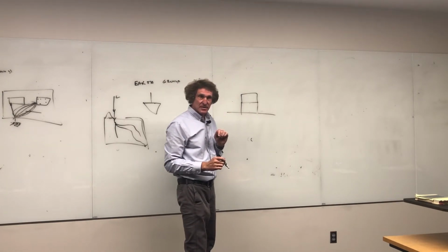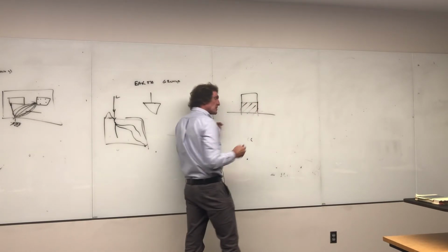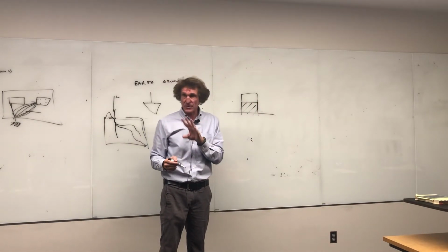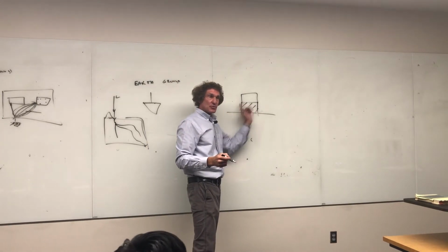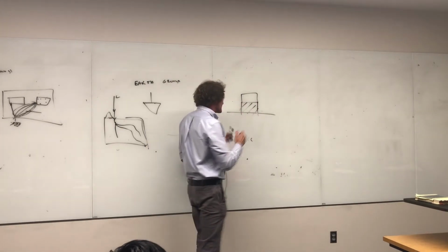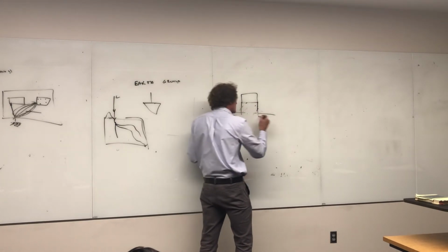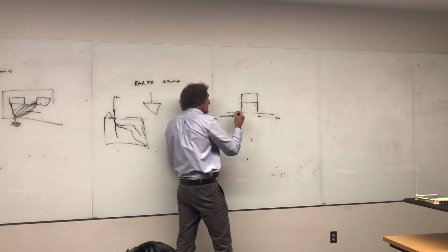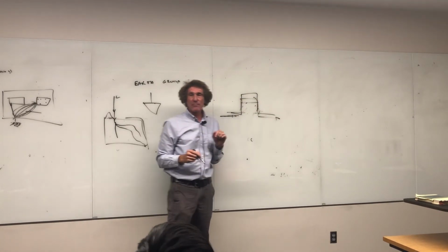And the reason is this. If you get 2 points, there are several things. This becomes a loop for starters. So if you have time-varying magnetic fields in there, you induce currents in here. That's the first reason. The second reason is when you have 2 points, if heavy currents like a lightning hit happen here, then some of that current can shoot right through there. You follow me? If you have more than one connection.